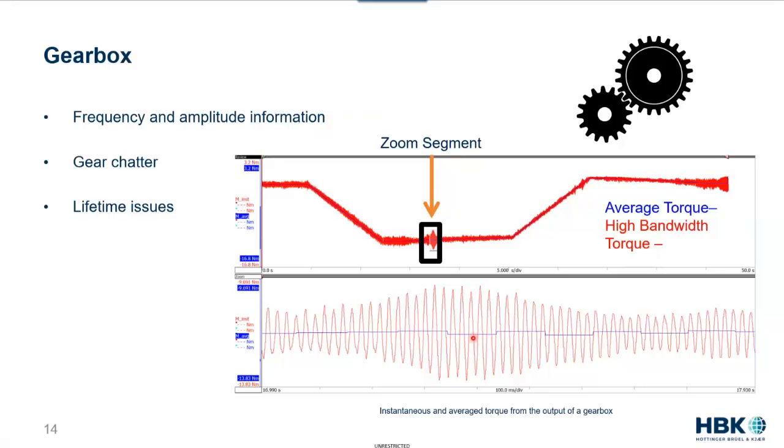And that can really be a problem in the situation with a gearbox because a gearbox can multiply or divide torque, so increase or decrease it. And knowing the peak values of torque being experienced by system components can have a big effect on the lifetime of those components and how well they hold up in the application.